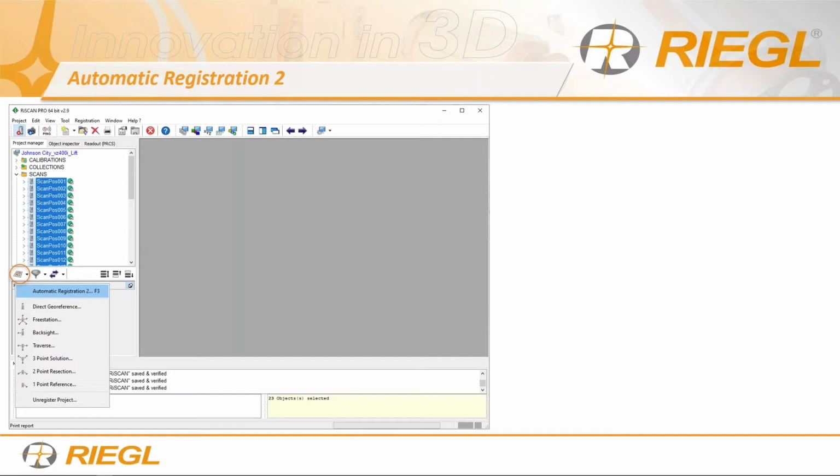You just click on that little map grid icon, or hit F3 for shortcut, and then select automatic registration 2. Now, as you can see from here, we also have other methods to register the data, right? So we haven't really taken away any traditional stuff. We've just introduced the automatic registration tool. So we have the backsight, the traverse, free station where you're just throwing targets out there and tying it down, resection rather, and then 1 point reference, 2 point reference. If you want to see any of those ones, let me know, and then we'll show you how to do it.